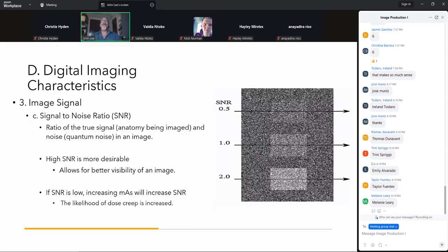Signal to noise ratio is the ratio of the usable factual signal to the amount of noise within the system that's normally there. Under all circumstances, there is a certain amount of noise within an electrical system, period. The object of our electronic imaging devices is to get enough image information, a larger imaging signal, to outweigh that noise so that we can see the details.